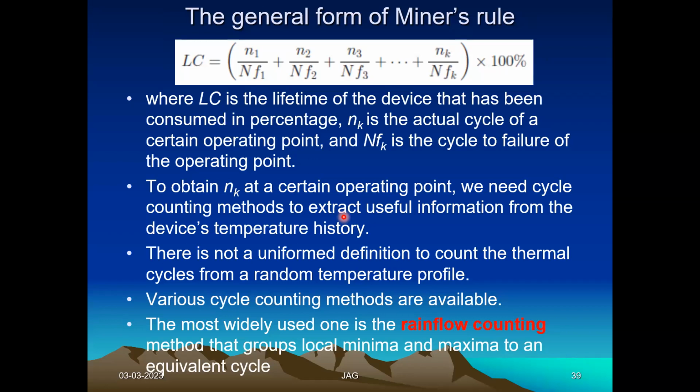For India, you have a road profile. In European countries, you have yet another road profile. For US, Canada, everywhere you have different road profiles depending upon the nature of the road, height of the road, width of the road, everything, right? So depending upon the road profile, you can calculate how many times my MOSFET will be turned on and turned off if my vehicle is running in that profile.